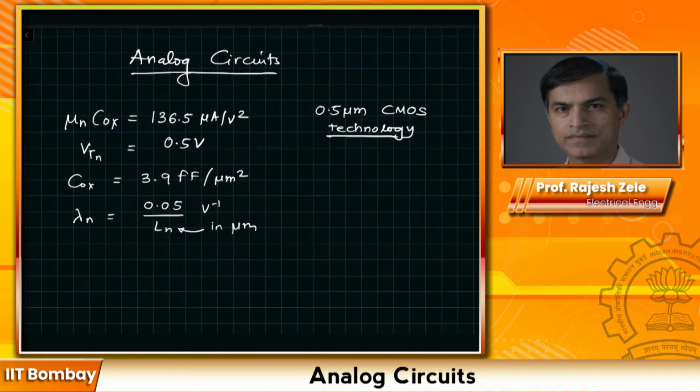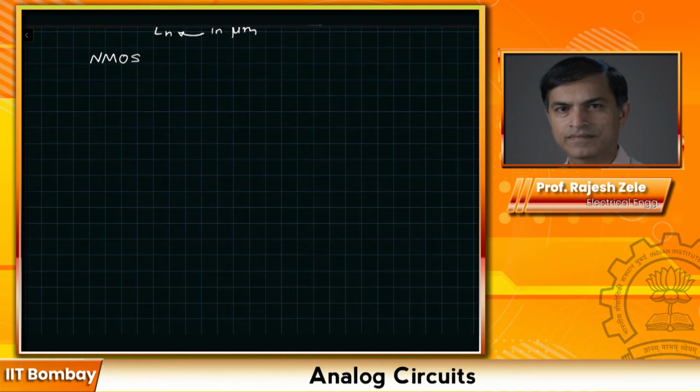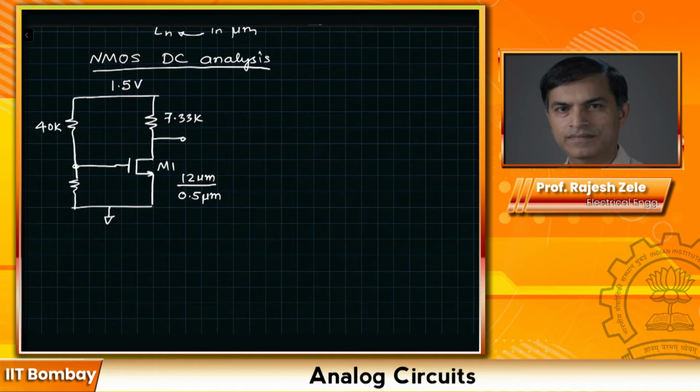So the first example we are going to go through is for MOS DC analysis. Let's write NMOS, very similar to our bipolar example. We have a resistor R1, which will start off with value 2k ohm. For AC input, we will apply a big capacitor here, and then we will apply our V in AC. We already went through the discussion about why we have the C big. Let me repeat that again.